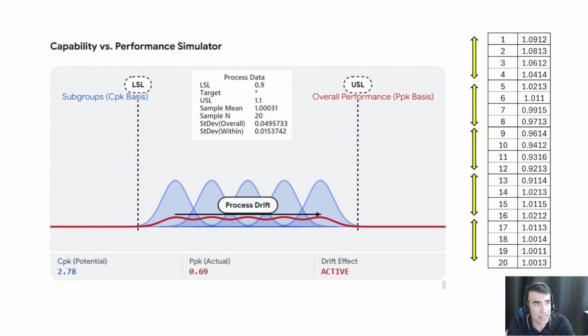If you look at the Cpk, then the time of measurement is important because you have subgroup after subgroup. So how you collect the data is important for Cpk, but for Ppk, it doesn't matter because it sums all the 20 samples together. So for this particular case, where we are randomly taking 20 samples out of the bag, Cpk doesn't tell us anything. What we have to look at is Ppk, the overall standard deviation.